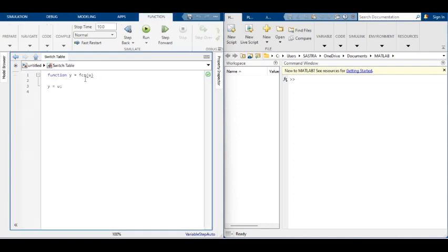In the basic H-bridge circuit, the positive voltage of the input is achieved by turning on one pair of switches, and the negative voltage of the input is achieved by turning on the opposite switch pair. The 0th level is used to provide the conducting path to provide different levels with the combination of another H-bridge.